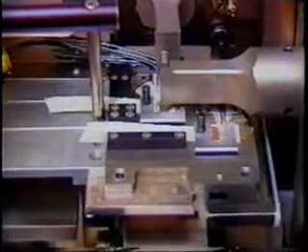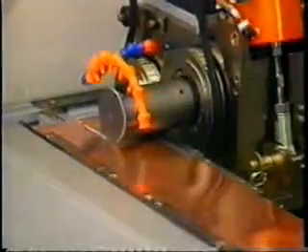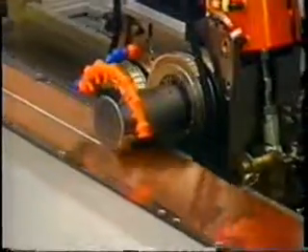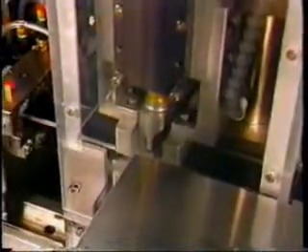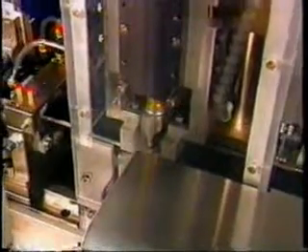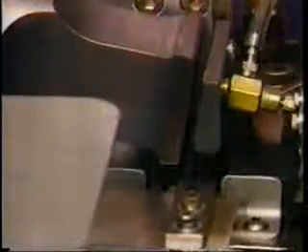Ultrasonic welding typically requires at least one of the workpieces to be thin. The usual welds are spot welds and straight or circular seam welds. Workpiece distortion is limited. Ductile metals in similar or dissimilar combinations are ideal workpieces, although hard metals also can be welded. Filler metals are not normally required, although they can assist in joining difficult-to-weld dissimilar metals.